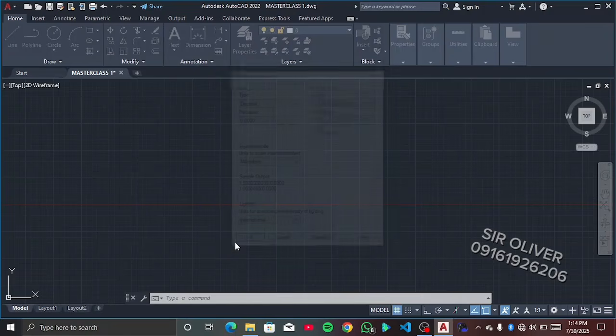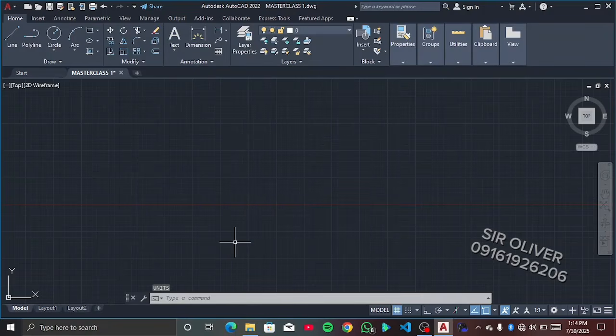This unit, like I said before, doesn't actually affect anything in the model space. It is only when you are dimensioning and when you are plotting or printing that you can see the effect of these units I talked about. But aside from that, units are not all that important. They are important, but not when you are actually doing the drawing. When you print it out, that's when you see the importance of setting your units, your dimensions and every other thing, like I said, and scaling.